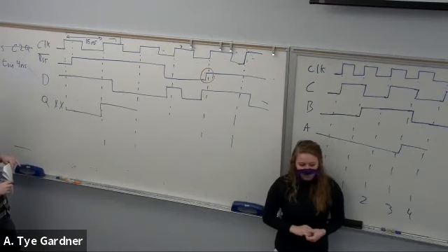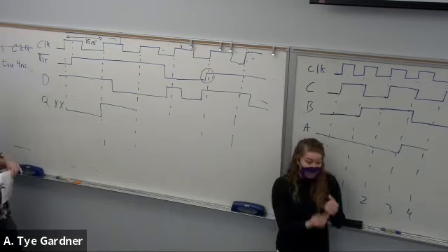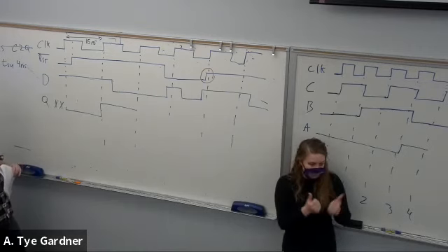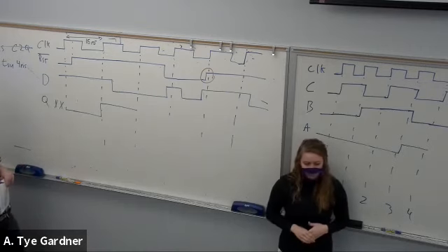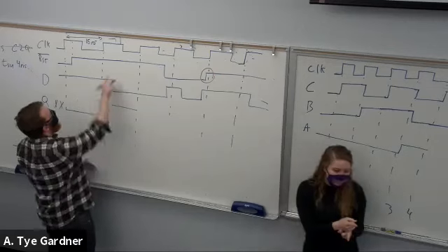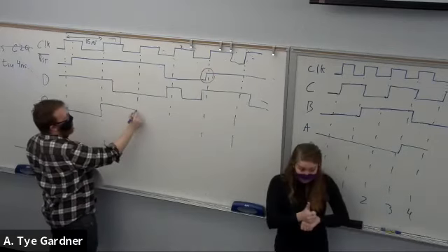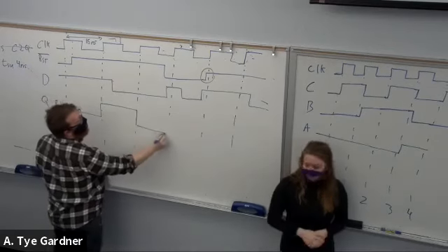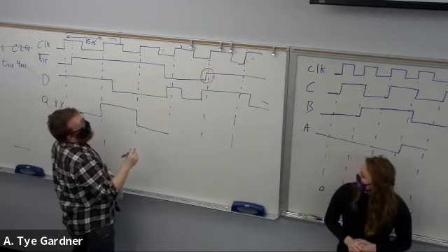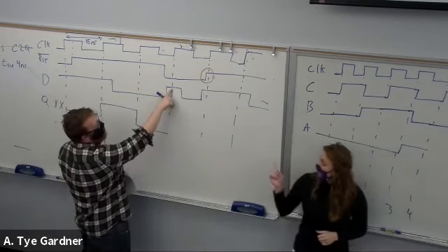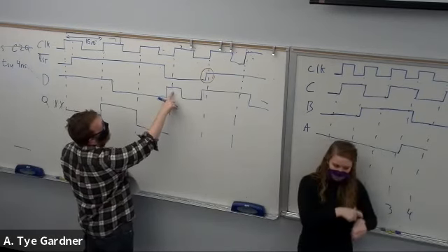Am I looking at reset or D data? Both. You need to take into account both, because it's a D flip-flop. I'm thinking it's going down to 0 then. Correct, because we're not resetting and D is 0. Great. Now, this one I said no hold time requirement, so that's okay.